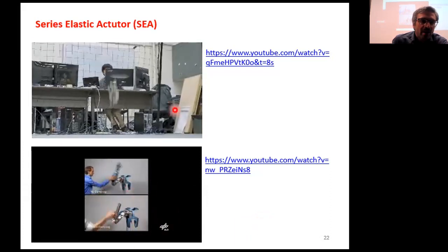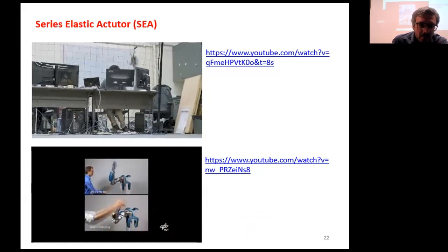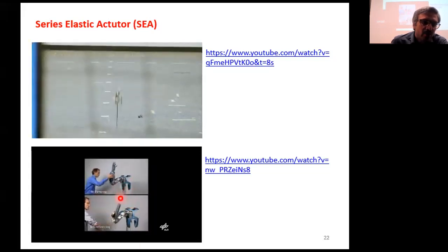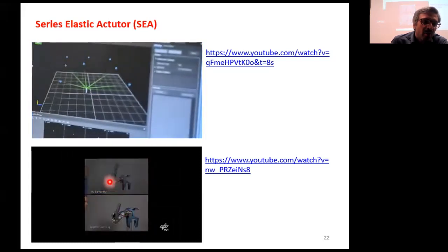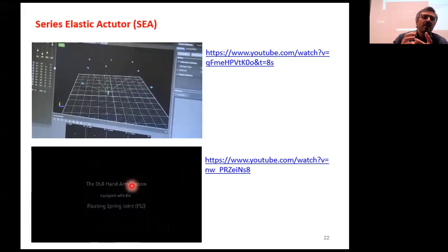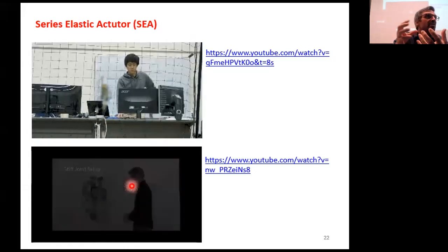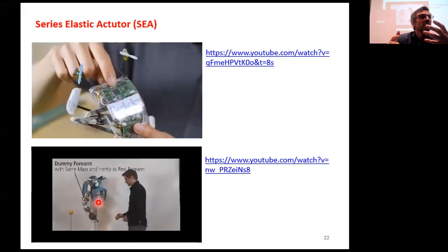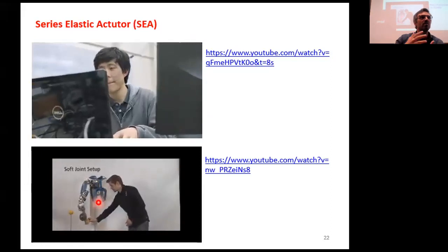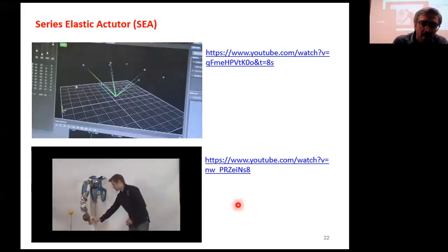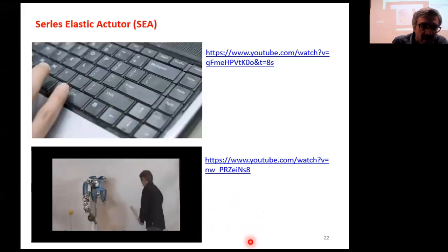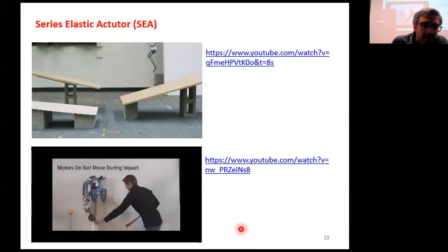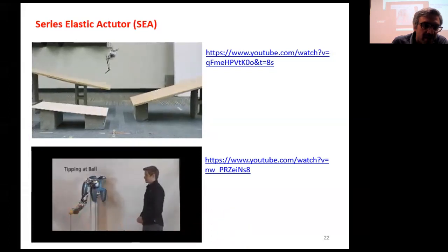Also in human-robot interaction, you can see that series elastic actuators are used to interact with humans. To avoid the problem of the spring, that if you only have a spring you will have infinite oscillations, people implemented some damping strategies with piezoelectric elements to remove the continuous oscillation and to have compliance, but also come back without any overshoot. So this is a work, I think, from the DLR guys, and it's very nice because you can hammer it and reject big impacts.